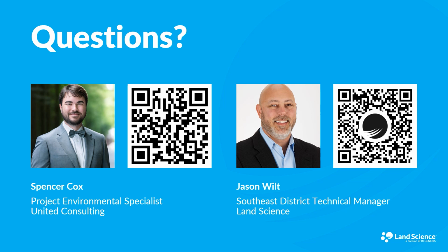They're used to just being able to slap down an elevator pit base, sidewalls, and keep moving. And those sometimes can be huge integral portions of a remediation system. Elevator shafts tend to cause uplift pretty quick and draw vapors in very quickly and push them to higher floors of a building. So it's very important that they're mitigated properly and that they're communicated on the front end that they need to be mitigated properly as well.